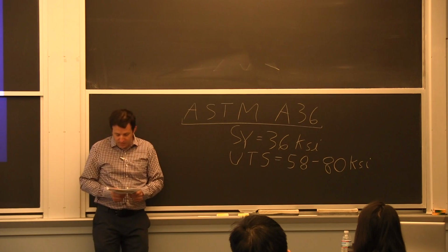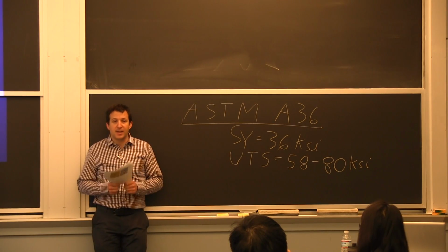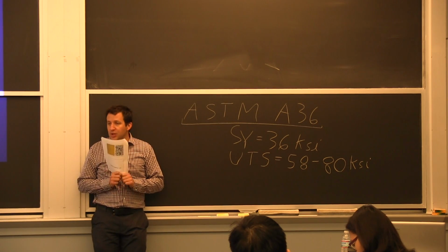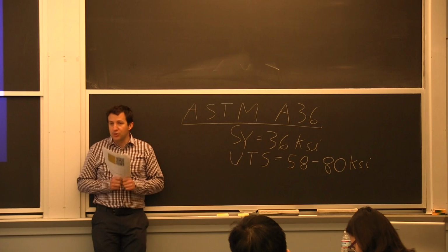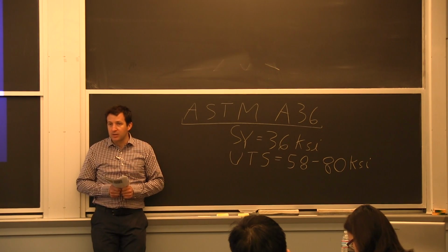A lot of steel specifications also have maximum hardness in these ASTMs. And some of that is to resist hydrogen embrittlement or hydrogen-induced cracking. There are very specific reasons for putting them on.